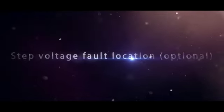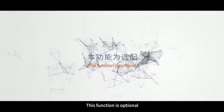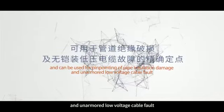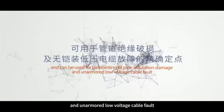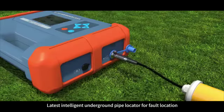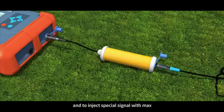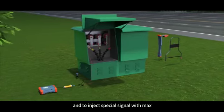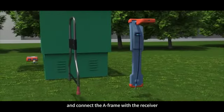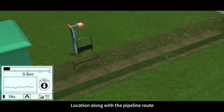Step voltage fault location, optional. This function is optional and can be used for pinpointing pipe insulation damage and unarmored low-voltage cable faults. The latest intelligent underground pipe locator for fault location: connect the booster with the transmitter and inject a special signal with max 1 kV voltage to the fault cable. Connect the A-frame with the receiver, and locate along the pipeline route.